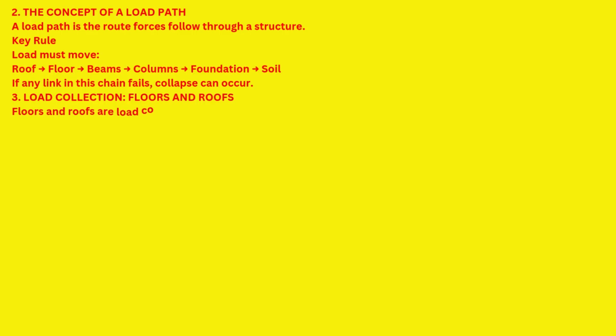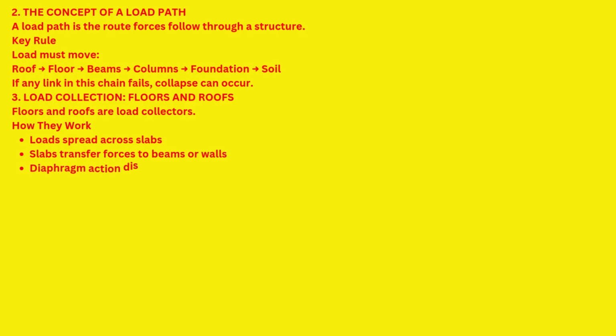3. Load collection. Floors and roofs. Floors and roofs are load collectors. How they work: loads spread across slabs, which transfer forces to beams or walls. Diaphragm action distributes horizontal loads. They act like trays, gathering weight and passing it onward.